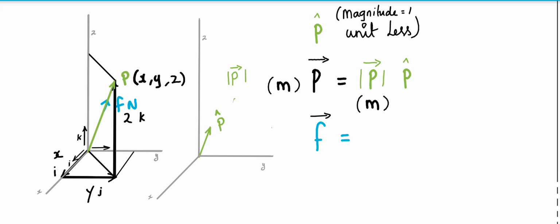You can see here the force is also acting along the same line. You can say it as a rope, so it acts along the rope. If I want to find this F vector, first this has the same direction as P vector. So P cap vector, that is unit vector of P, the direction of P, is equal to the direction of F. So I can substitute like this: the direction of F vector is equal to this direction of P vector.